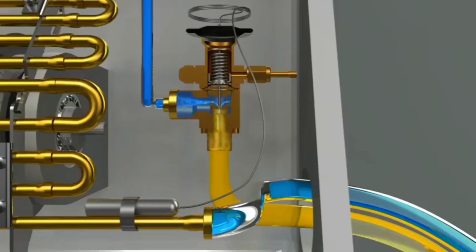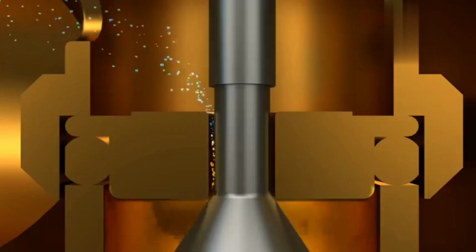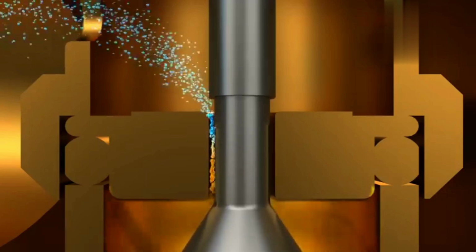The expansion valve is connected to a sensing bulb that detects heat. The sensing bulb is installed on the exit of an evaporator and detects temperature. Inside the bulb is fluid sensitive to temperature changes, and as the temperature at the exit of an evaporator rises, the gas pressure rises, which in turn presses on a spring to send more refrigerant to the evaporator.